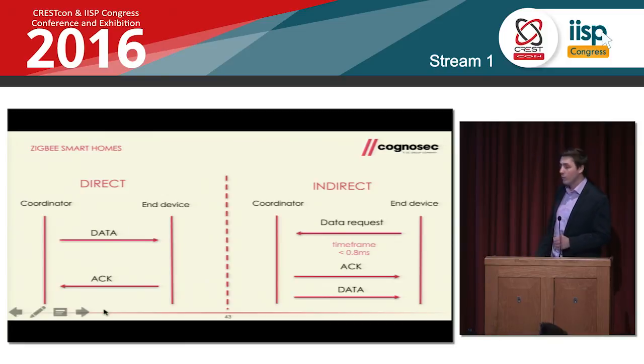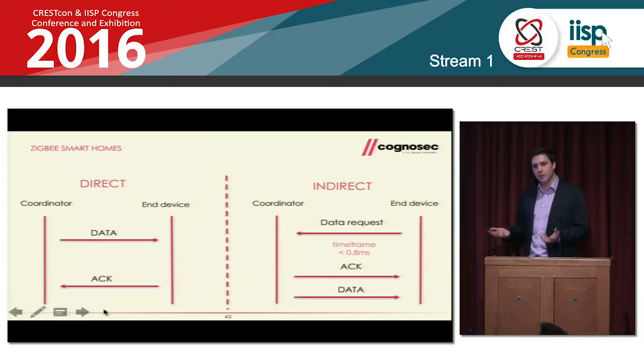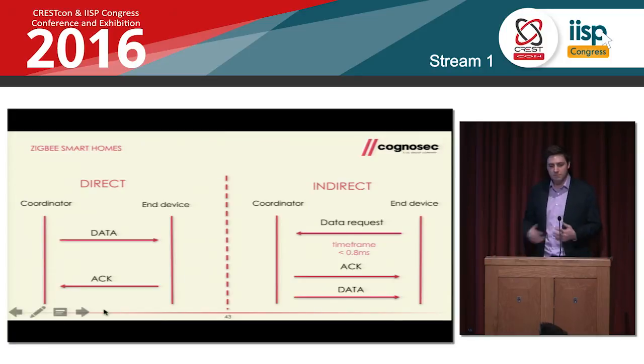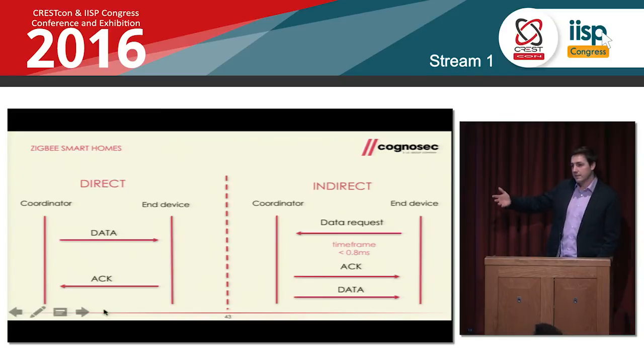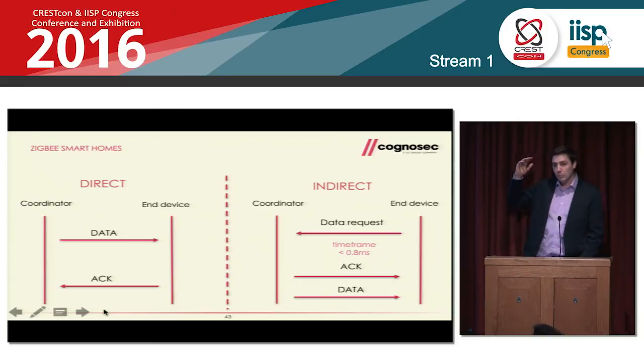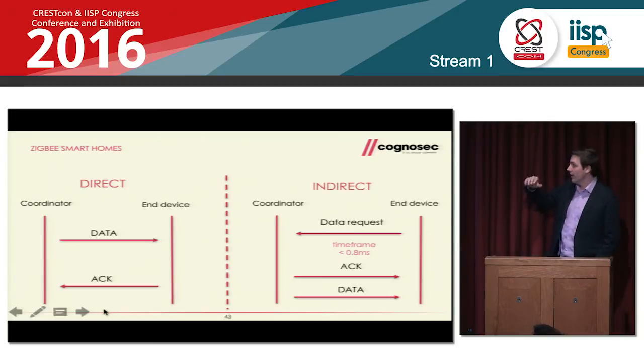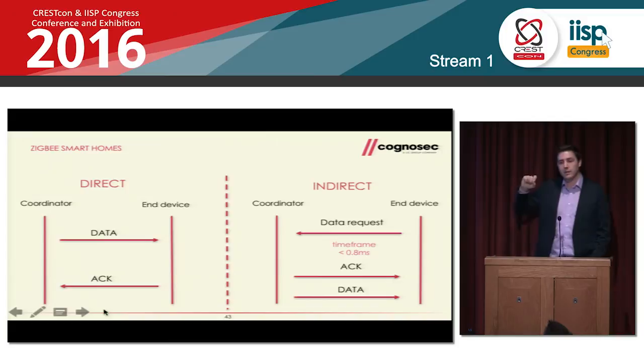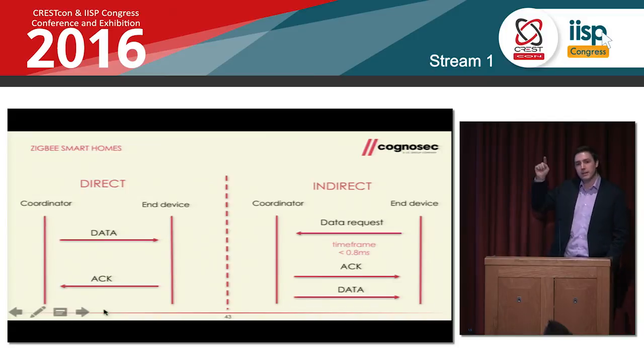And we always wanted to control the door lock because that's the funny part, and the door lock is battery powered. So we always just sent our data requests to the device and we never got it, nothing happened. Because the problem is the door lock wakes up every 5 seconds and sends a data request to the hub, and within a very short time frame, the hub sends an acknowledge, and there is a flag in there indicating whether there is data pending or not.